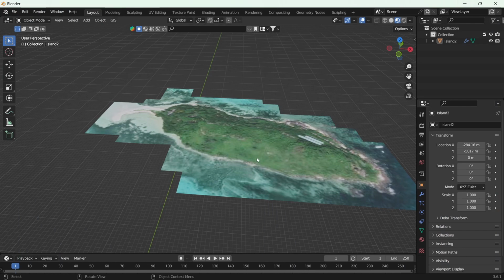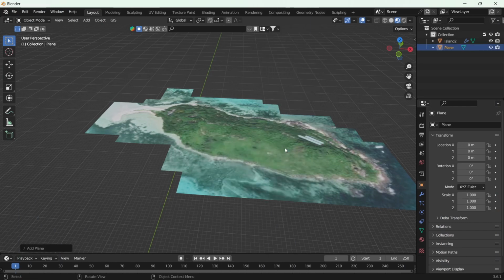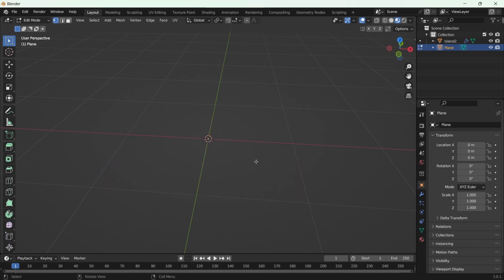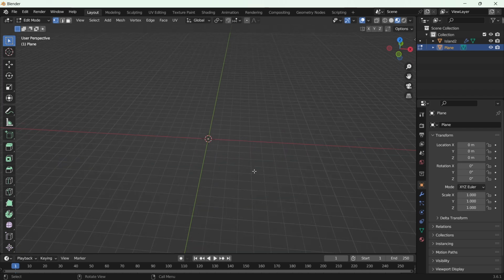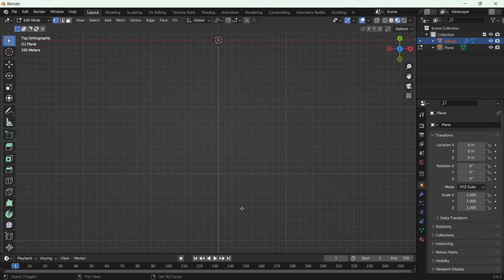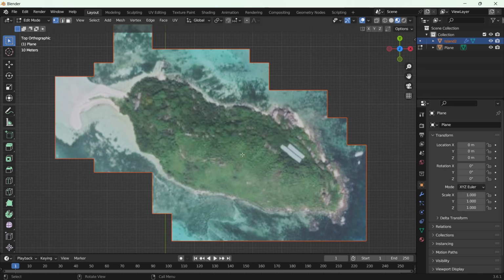The first step is to flatten the area where the road will be made. Let's trace the path the road would follow. Create a plane, and merge all its vertices at the center, in edit mode. In order to trace the path, we are going to extrude the vertex. You can use a NURBS path or any other curve as well. However, the advantage with using mesh vertices is that it is easier to align the roads at intersections. In case your road doesn't have intersections, using curves is a better option.